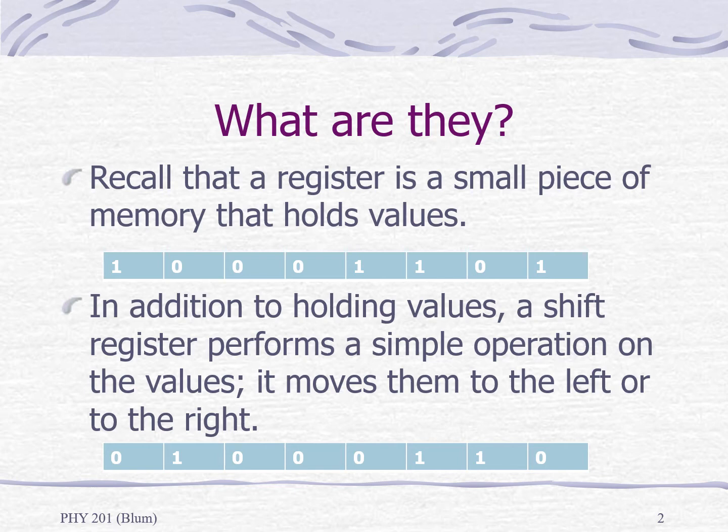A shift register adds another operation to the job of the register. The job of the register is to hold, and the job of the shift register is to hold and also to be able to shift, to move all the bits in one direction or the other. So here we've shown a shift to the right.